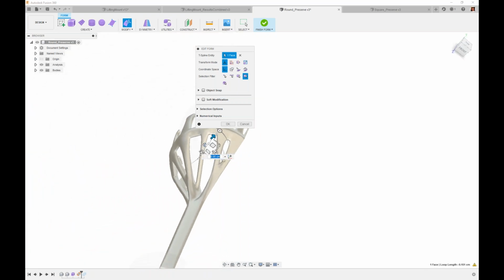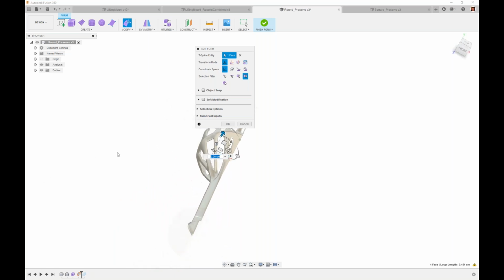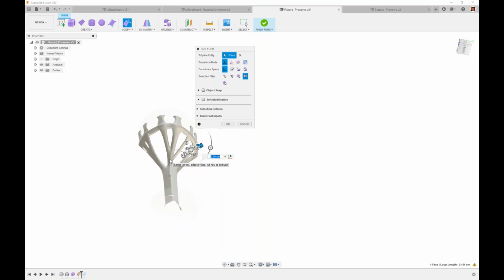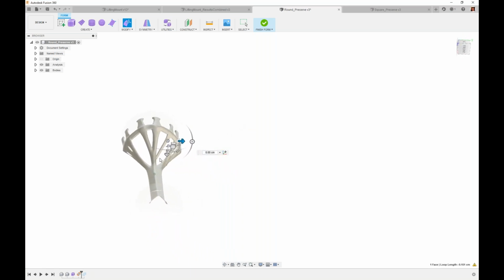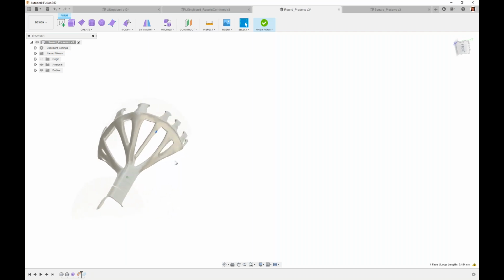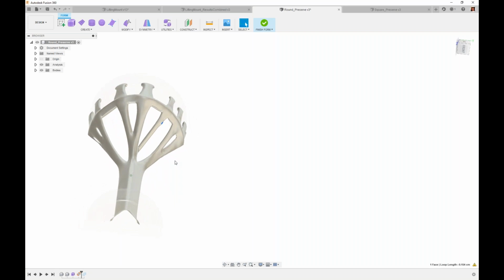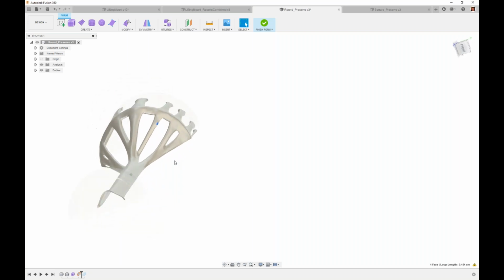In a similar fashion to the prior question around symmetry, there are times where, if I liked the right side better than the left side, even doing an extrude cut and then mirroring the side that I liked to guarantee symmetry about a specific plane.